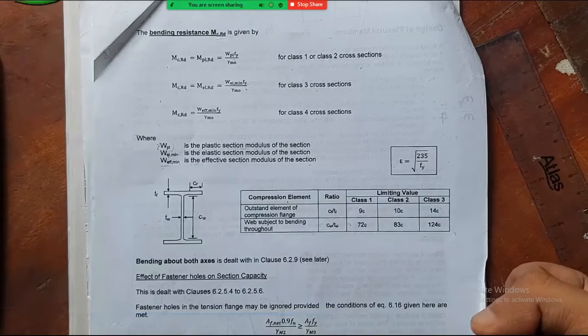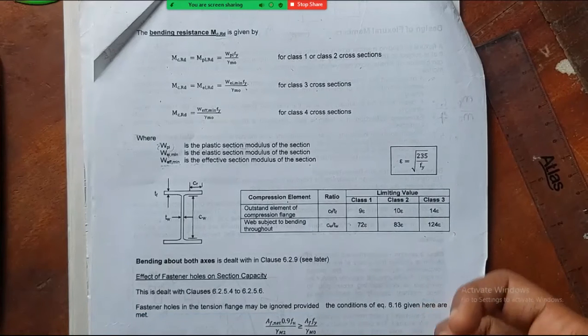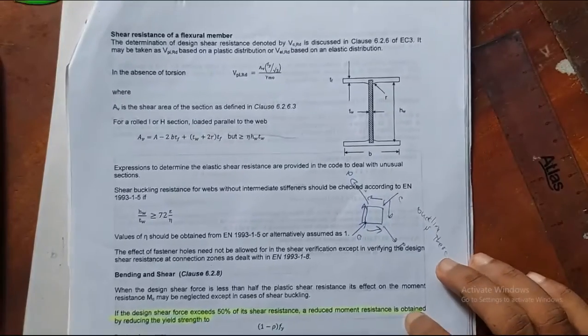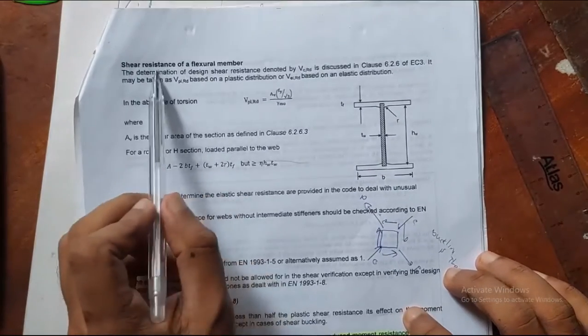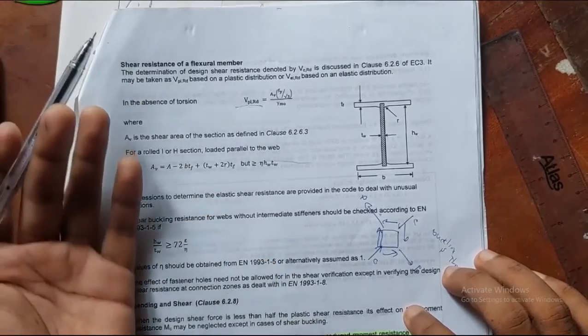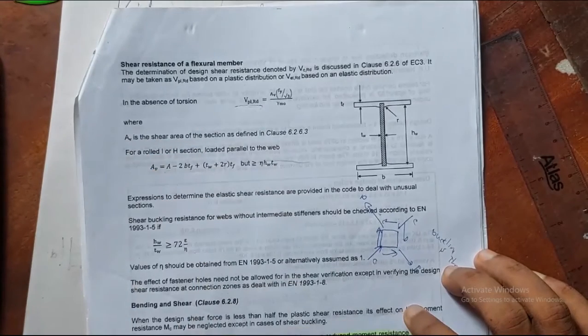They give you the bending resistance or the shear resistance based on your section. You just need to adapt it, calculate your values and check that they do not exceed the given values. So we'll do an example. You can even see this: the shear resistance is given, so you only need to check whether your shear value is larger than this. If it is larger, your section is not safe, so you will probably have to change your shape.